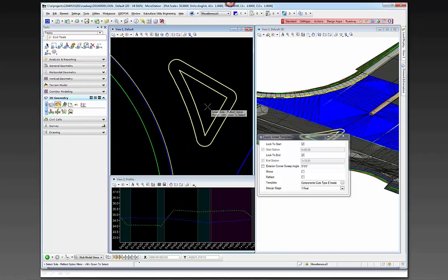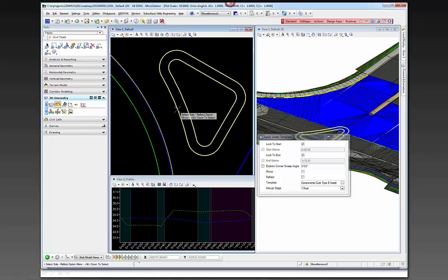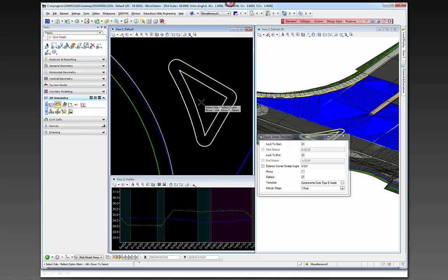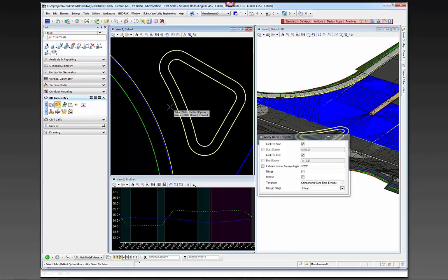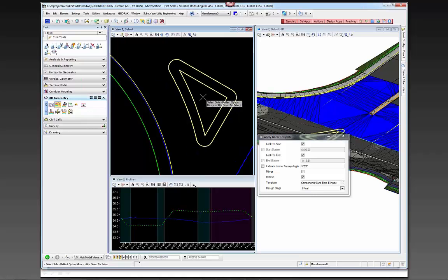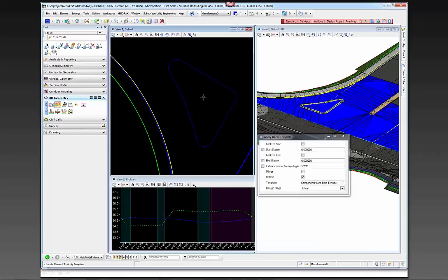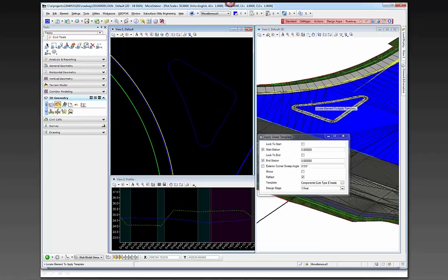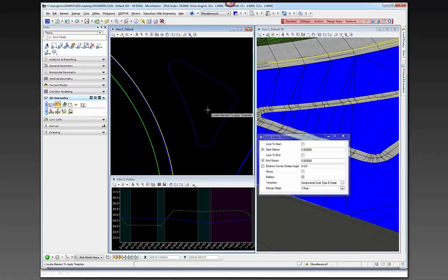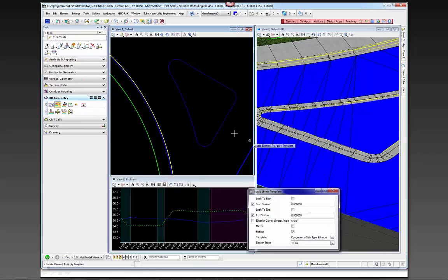And then the reflection, this is the direction that you're going to place the curb. So you got a 50-50 shot if you don't know where your template origin is. In my case, I'm pretty sure I need to go in this direction, and then I just give it an exterior boundary or exterior angle, and it creates that curb all the way around that element.